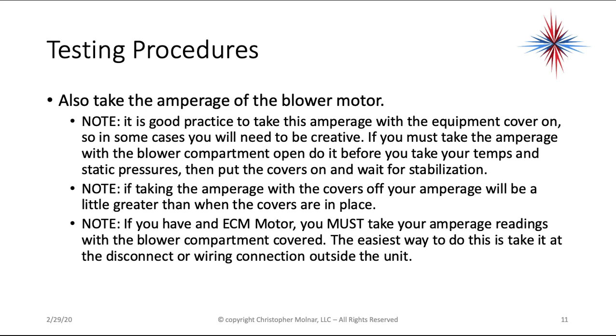Also take the amperage of the blower motor. Now, it's good practice to take this amperage with the equipment cover on. So in some cases, you do need to be creative. If you must take the amperage with the blower compartment open, do it before you take your temps and static pressures, and then put the covers back on and wait for stabilization.